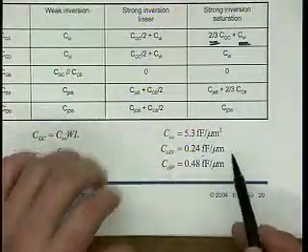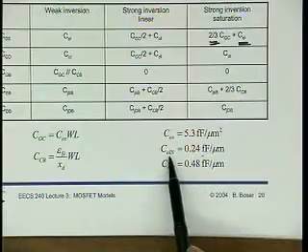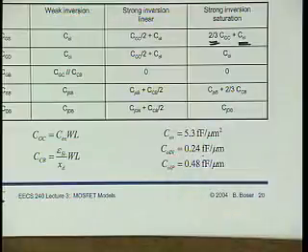0.24 femtofarads per micron. So if you have a transistor with width 100 micron and it's an N channel, then the overlap capacitance is going to be 100 times 0.24, 24 femtofarads. The overlap I get for the PMOS happens to be just twice as large. In another process, of course, it wouldn't necessarily be twice. They are not always the same. So that's how we calculate the overlap capacitance.